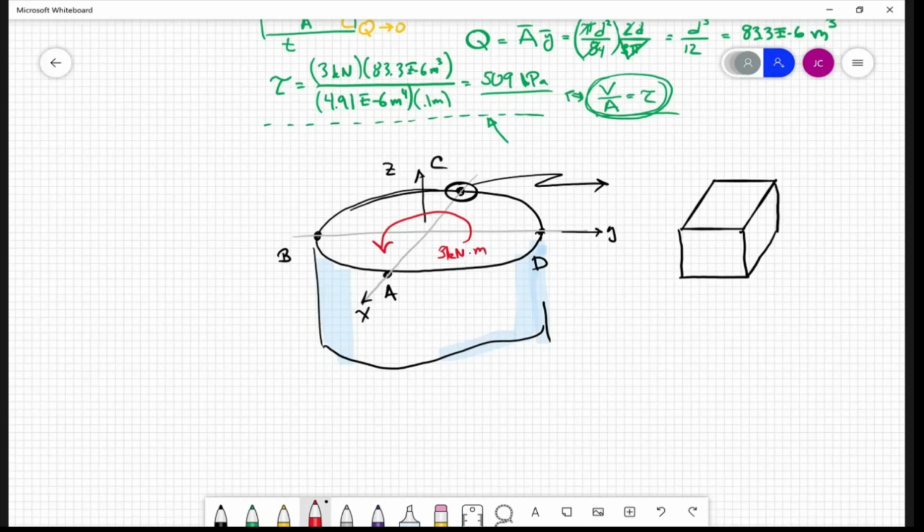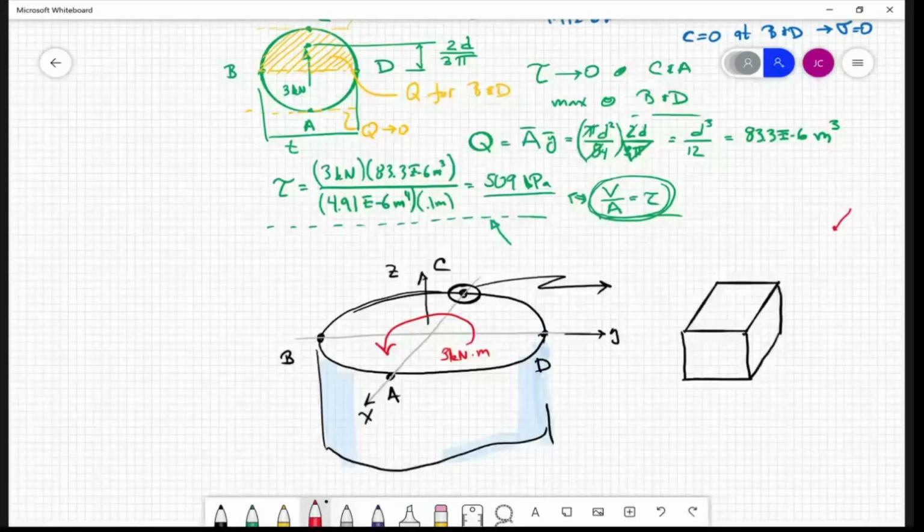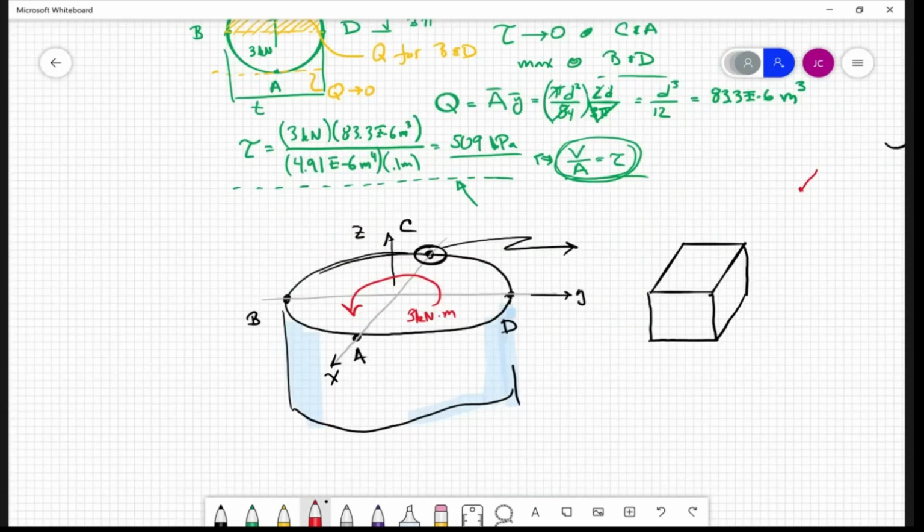All right. Well, how does that show up on this little cube of material? The 15.3 megapascal stress. So we know it's a shear stress, correct? What plane does that shear stress act on? On the XY, I think.